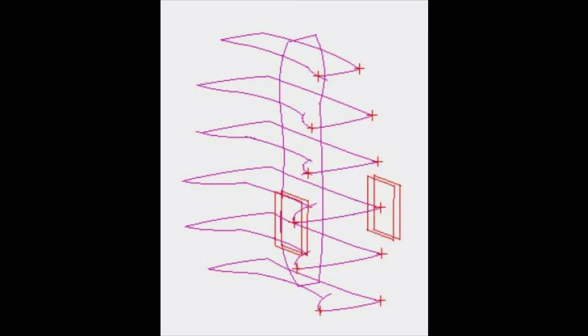Continue using the same method on the side surface as the bolster surface. Trim the side curve to the planes which were just created and create the end point on this curve. Now create the limit curve through these points as smooth as possible, using the analysis technique mentioned previously.